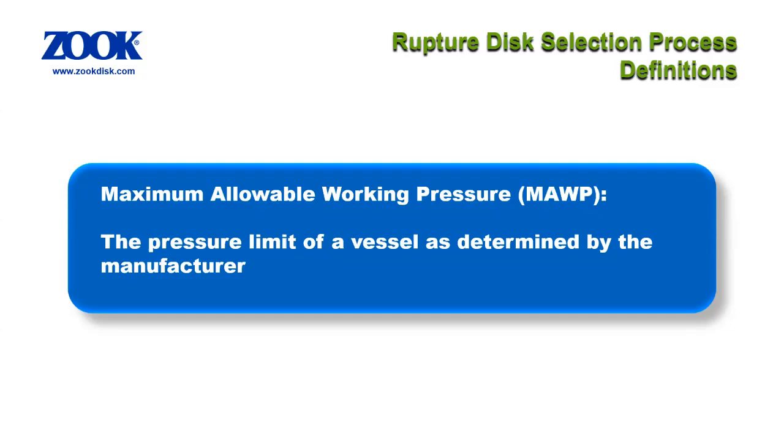Choosing a burst pressure below or well below the MAWP is fine. However, this may affect the service life of the rupture disc when operating closer to the system operating pressure. As such, the MAWP forms the basis in the pressure setting and sizing of the rupture disc. So it should be noted that choosing a rupture disc burst pressure lower than the MAWP will result in a larger disc size during sizing calculation.